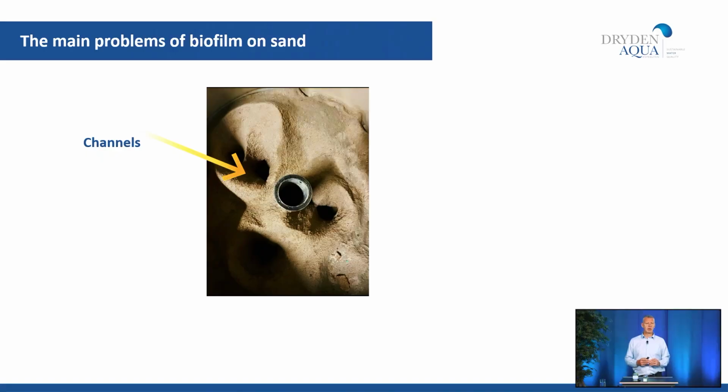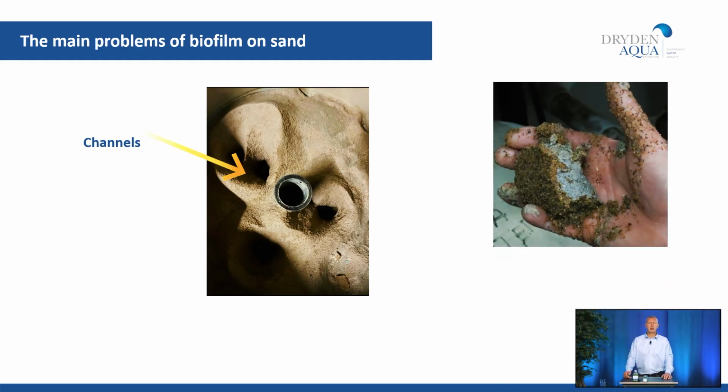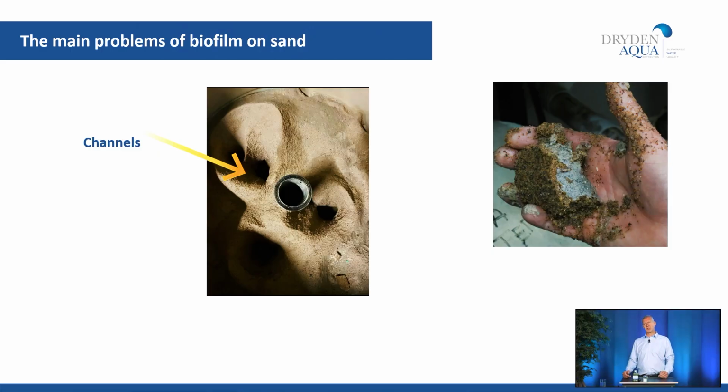This is a great example of wormhole channeling in a sand media. And if you've ever had the pleasure of going out and doing a media change, you'll know full well it's not the most pleasant job on the planet, particularly when you get down to the bottom of the filter, around the collection system, the nozzle plates, the laterals. This is really where we see a lot of biocoagulation going on, and it can be quite an unpleasant task. I do like the good use of PPE gear in this picture. Not.